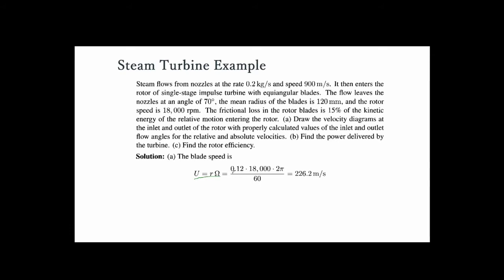So we just plug in the radius 0.12 and 18,000 rpm into this equation. We will get the blade speed equal to 226.2 meter per second.